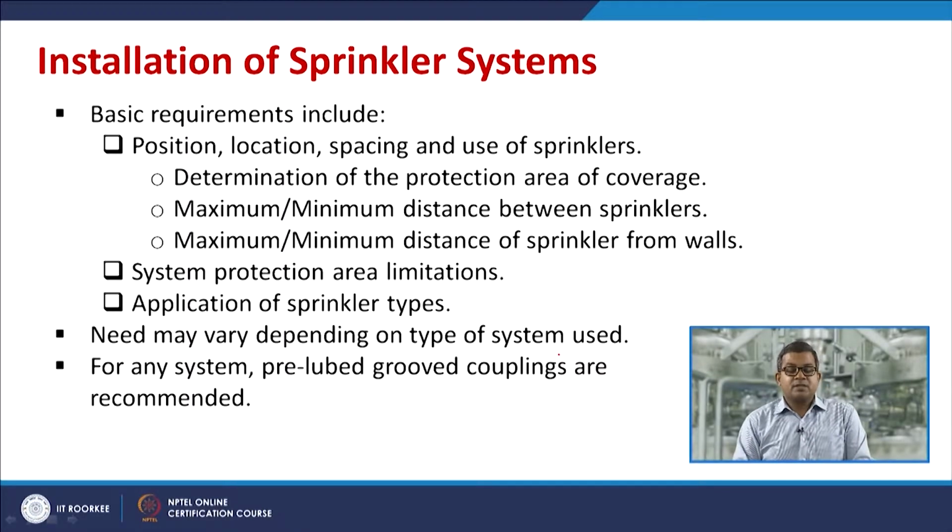Then you need to find out which applications are applicable to various sprinkler types, because in the previous modules we have discussed different types of sprinklers. So which kind of sprinkler is applicable to what? You need to find out all those things. These needs may vary depending on the type of system you are using, such as position, location, etc. For any system, pre-lubed grooved couplings are always recommended.